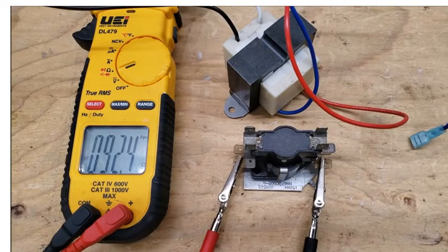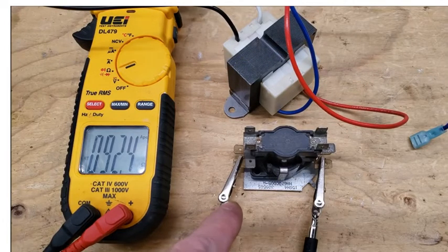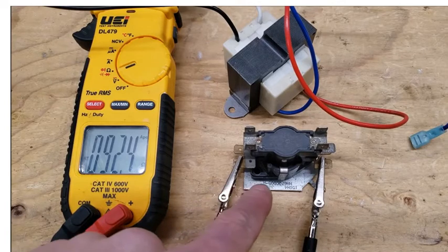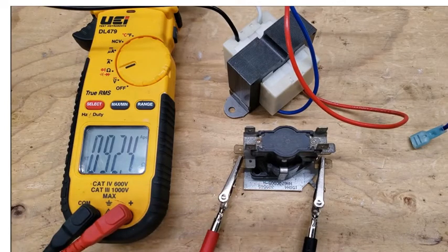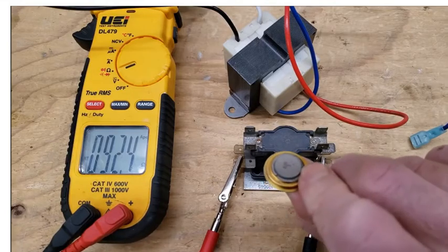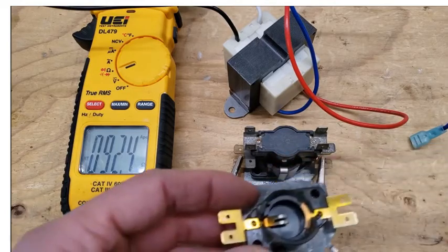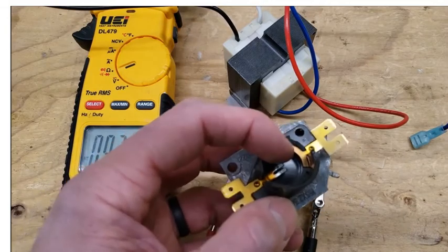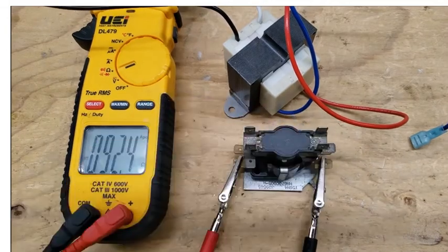So in reference to troubleshooting, you can check to make sure that you don't have OL from one point to the other point for where you're going to connect your 24 volts at. Basically, all you're doing is checking the resistance value of this little pane heater, from one side to the other. So maybe one of these little brass parts right here melted or something like that, and that's why you read OL. If that's the case, the sequencer is no good.